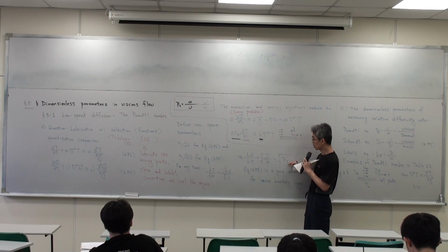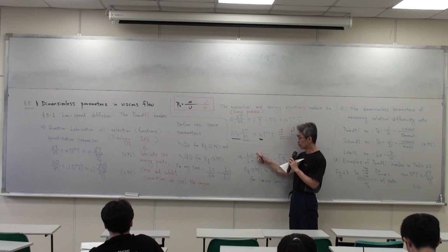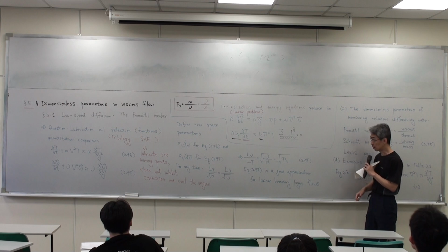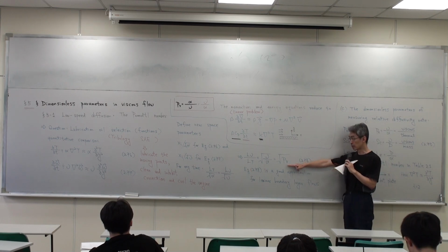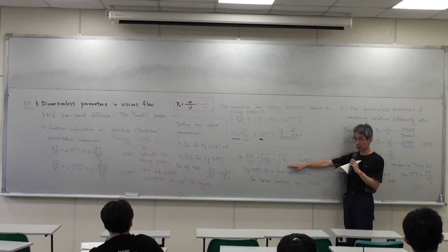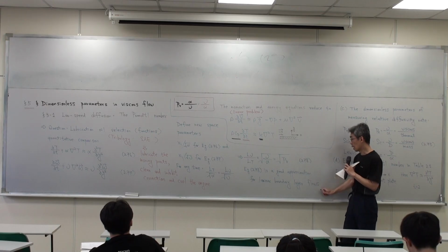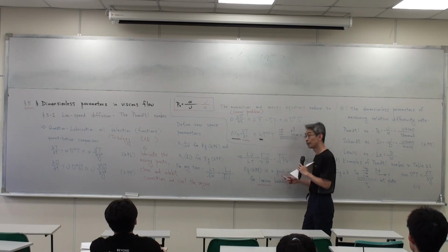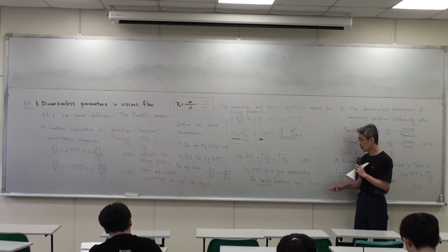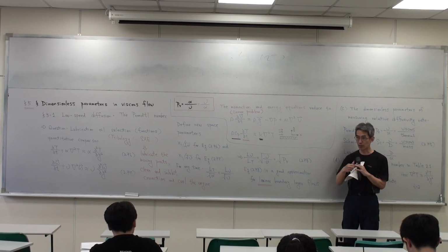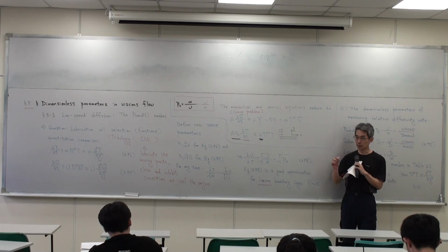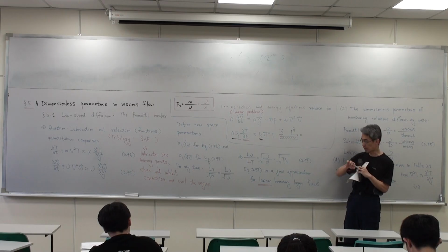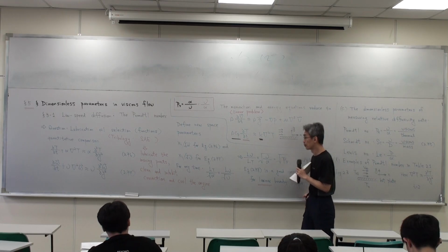Okay, so the Prandtl number compares the boundary layer by the momentum and the thermal boundary layer by the temperature, and they will relate to the square root of the Prandtl number. So using this, we can estimate the laminar flow. Okay, the boundary layer for the turbulent, that will be another story. They will be shorter and closer to the boundary. But here we talk about the laminar boundary layer.